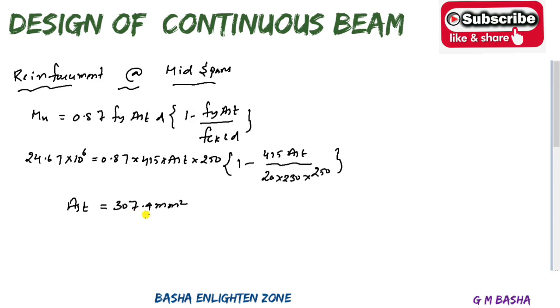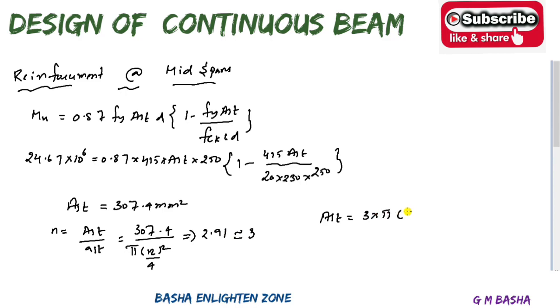For example, here area of the steel will be 307. Already we provided for this moment 367, which was 4 bars of 12 dia. If you want an economical calculation, you can check like this, what I told before. So that is 307.4. Again check with the same dia bar, pi d square by 4. How much will you get? You will get around 2.91. So here, one bar will be decreased, which is approximately 3. Check with the same bar, which is 3 into pi 12 square by 4. So it will be around 339.3 mm square. Comparing with the previous one, for this one you can select this, which means one bar will be reduced.